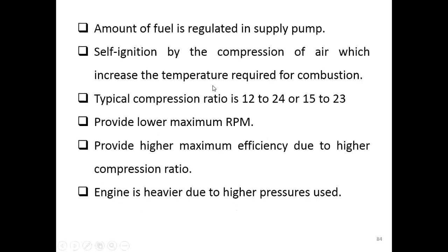Okay. The amount of the fuel is now not regulated by the throttle valve as in the SI engine. The amount of the fuel is now regulated by the supply pump. It is a self-ignition engine, which is done by the compression of the air, in which the air has the increased temperature that is required for the combustion. Okay. The typical compression ratio for this engine is what?